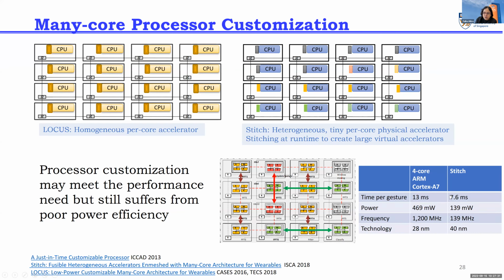Okay, so basically what the CGRA does is it combines efficiency with programmability. If you look at the Google TPU, for example, it's a specialized architecture. It can only do matrix multiplication, and it has been designed specifically for that. Whereas the CGRA can be configured in software to support matrix multiplication, and it can do almost as well, because it can create the same data flow on this particular hardware. But the advantage is that with a TPU, you are only able to do the GEMM, or maybe the convolution, but you cannot do the FFT.